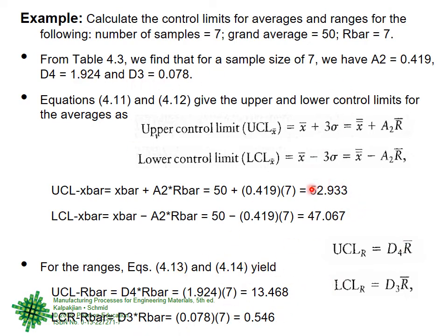So this is the upper and lower control limit based on the mean value. This is the lower and upper control limit based on the range. And this is how you divide it. If you want to be very strong in your judgment, then you don't do it only for means, you can do it for means and ranges. And if both ways it is under good statistical control, then you are very happy with your process. Otherwise, if there is any problem, then you look into it.